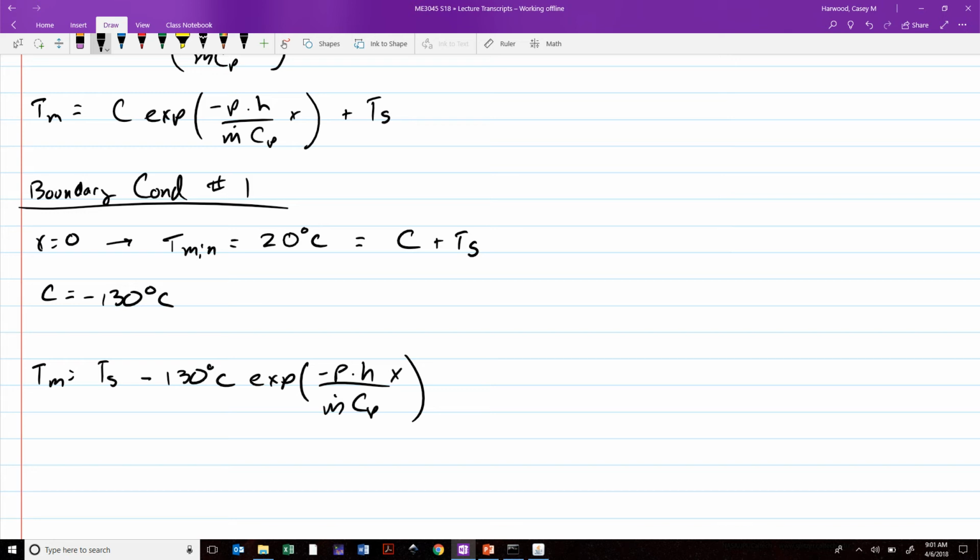Because, unlike before, we're not given h. We don't know Cp implicitly. So we're going to have to pull these data out of, as usual, the back of the book. So the question we need to ask ourselves is, we're talking about engine oil. If you look at the back of the book, the properties, in particular the convective heat transfer coefficient, the conductivity K, which is going to be important for redimensionalizing our Nusselt number, and Cp here, are all highly dependent on temperature. So what temperature do we use to look up those properties from the back of the book?